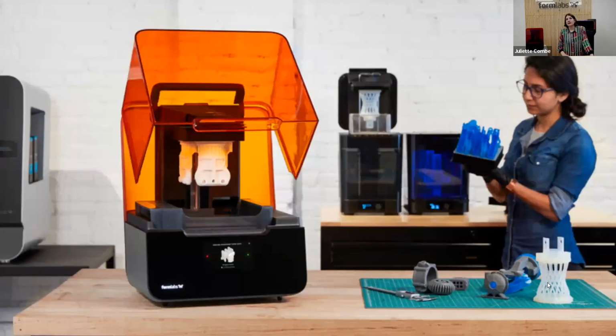So first, SLA, stereolithography. As I mentioned, it uses a laser to cure a liquid resin that hardens into a plastic. And this technology is very good for clear details and very smooth surface finish. So it really gives a great aspect on the surface of your parts, beautiful parts, and good accuracy as well. So I will always favor SLA when you need to produce beautiful parts.